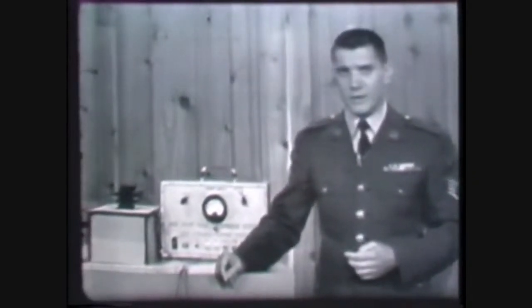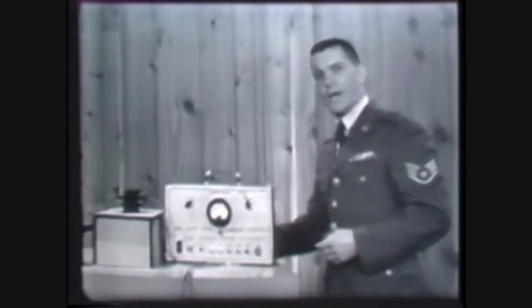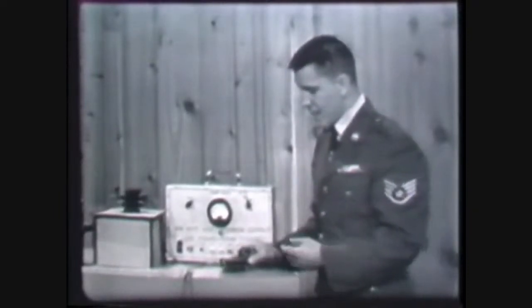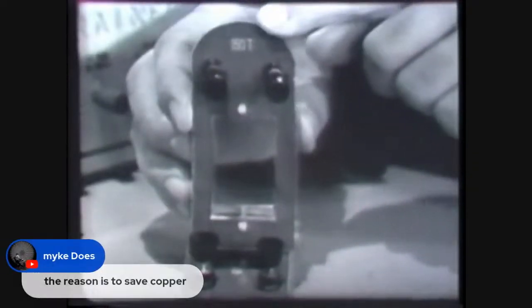Now, two other checks you'll have to perform on transformers quite frequently are those for an open or a shorted winding. Both of these checks can be performed with an ohm meter. Over here I have two windings identical to the windings we're using in our transformer. One of these windings has 150 turns.